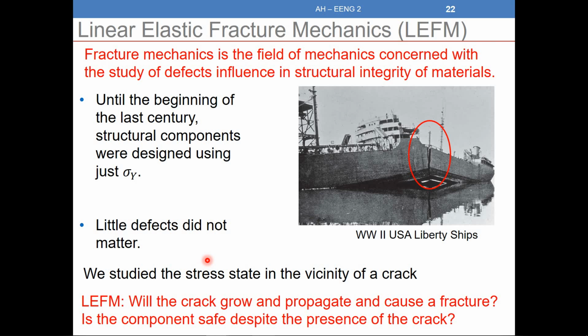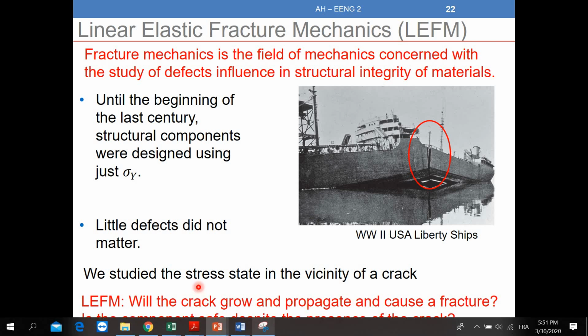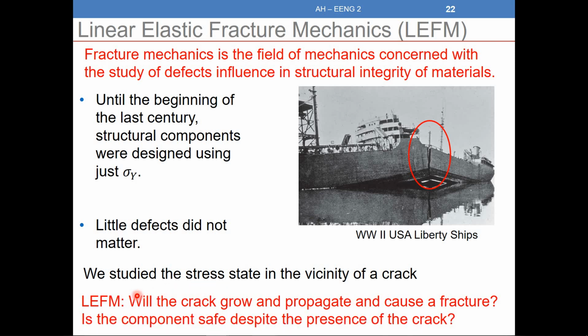But after that, we found that in some cases even a small crack can cause the failure of a large mechanical system. So everything we studied now about the cracks and about the stress intensity factor, we need to understand how we use it in order to check if a crack will propagate and cause failure or not. So that's the objective of linear elastic fracture mechanics. Will the crack grow and propagate, and what are the conditions under which it will or it will not propagate?